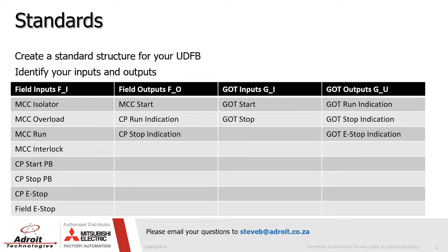Then I've set up a GOT program for us, which we're going to simulate together with the PLC program, where we'll have a start input and a stop input to the PLC, and feedback from the PLC when we have our run indication, stop indication, and e-stop indication.